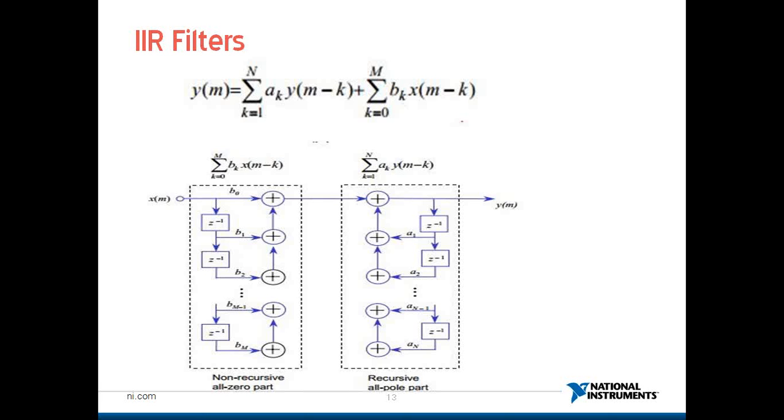So let me just quickly tell you a few of the criteria that you would have to keep in your mind when you are given a task to design a filter. Firstly, study the transfer function. After studying the transfer function, the second thing that you're supposed to do is the memory usage. How much memory are you allowed to use on the electronic circuit? The third criteria would be the coefficients. So again, the number of coefficients that you have would also decide the requirement of the memory. Third is the requirement of linearity, whether linearity is required or not.